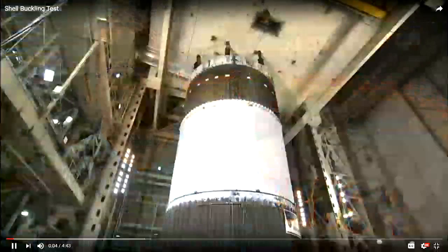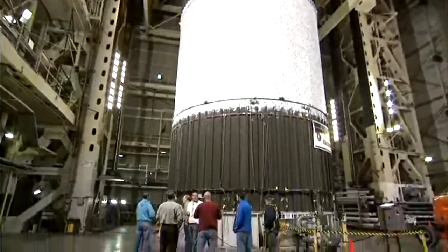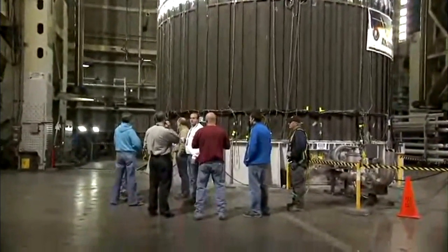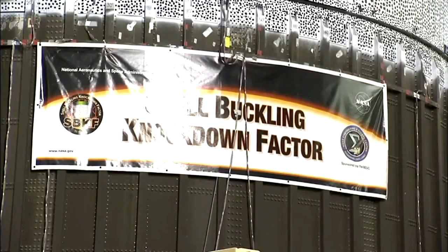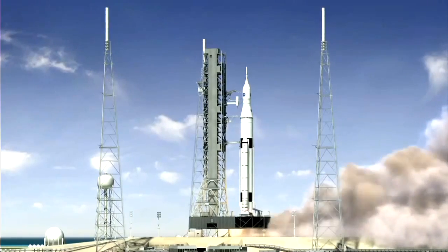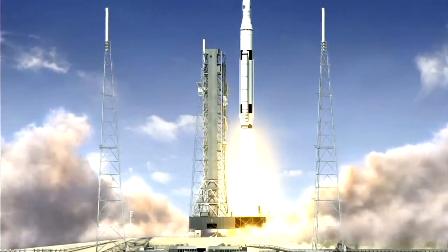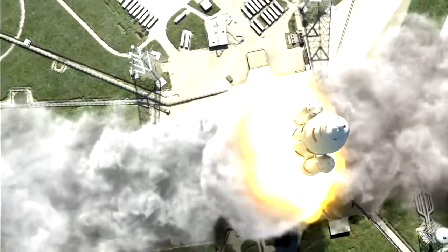The test article is a 27.5-foot diameter, 20-foot tall aluminum lithium orthogrid cylinder, very similar to the types of cylinders that were flying on the Space Shuttle external tank. In fact, this test article is derived from some excess hardware from the Space Shuttle program. So it's configured very much like the future SLS core stage tank structures, so it's very relevant to what NASA is designing today. In this test, we're going to be trying to simulate a lot of the same types of loads that a launch vehicle would be subjected to during flight.